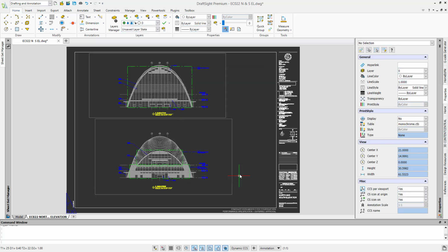And again, the great thing about the Page Layout Manager is if you are sharing DWG files with other teams or other disciplines, you no longer need to attach an associated configuration file with it if they would like to print it. All those settings are saved within the DWG itself, which is a real time saver, and you avoid a lot of headaches and attaching additional files.